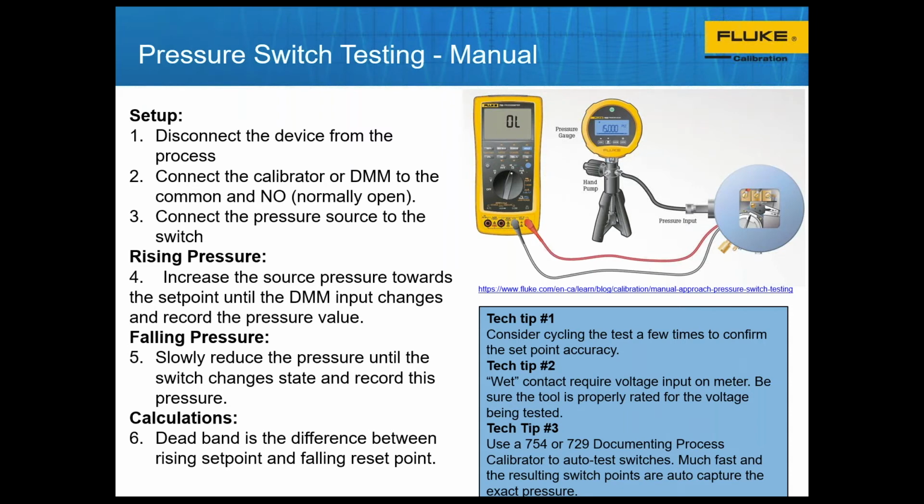We're going to want to document what that deadband value is, and then cycle through that particular 2 or 3 times to make sure that we have some continuity between them, and the switch itself is switching on a regular basis. Depending on how you've set up your process, you may want to capture the maximum value for that set point, the minimum value for that set point, or the average of those set points that you've measured. And that will typically require that you've gathered a bunch of data and you're going to do some analysis afterwards. But the process to go through this is pretty simple.